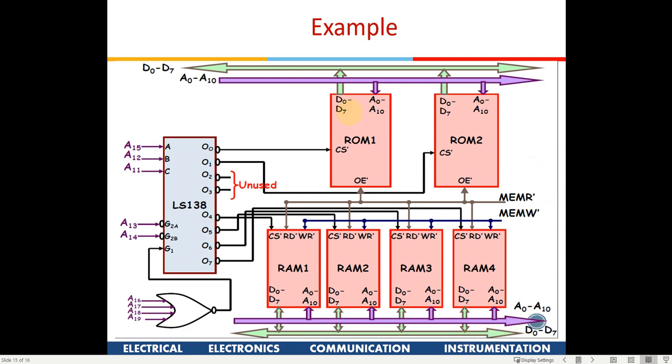And this is the kind of diagram which you will be expected to draw, at least in your comprehensive exam. So you'll have to show after the configuration what the interconnections are. You'll have to show the data lines which are connected. Because it is an 8-bit processor, the 8088, there are only 8 data lines, 0 to 7.